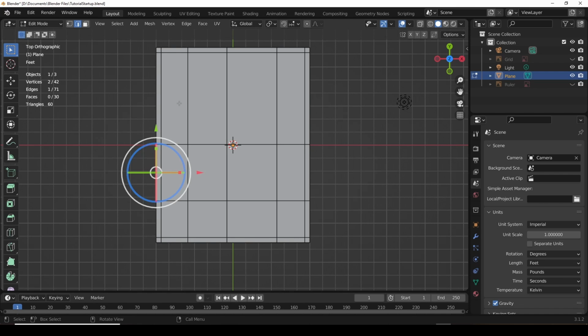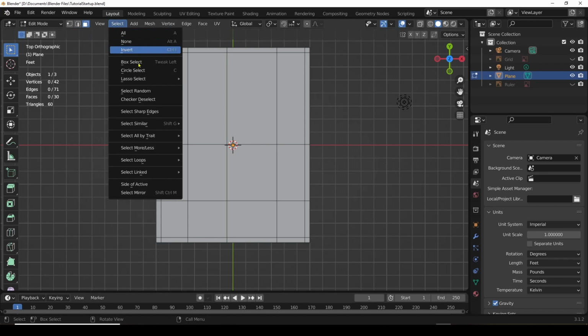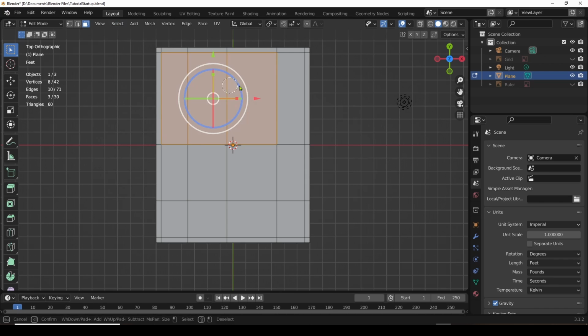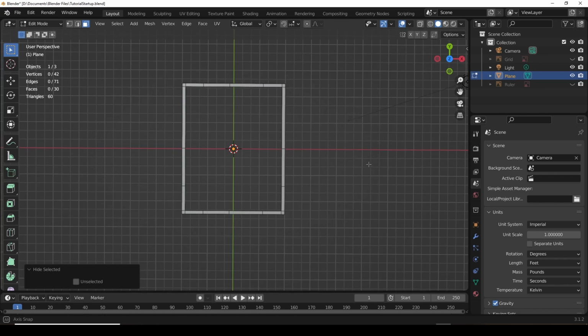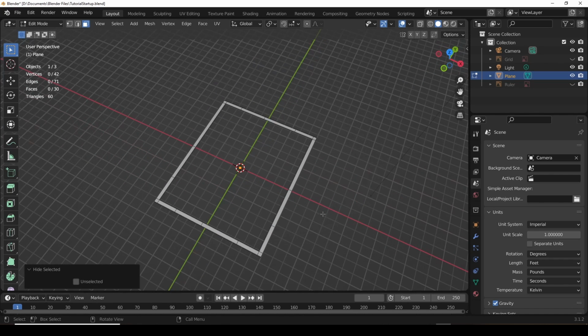We said before that it's really nice to get rid of or hide the things that don't matter. Now what we want to do is select those wall faces so that we can extrude. We don't care about this stuff. So I can go into face select mode, use circle select, select all these faces, and hit the H key and hide them. So now I'm just working on the walls.